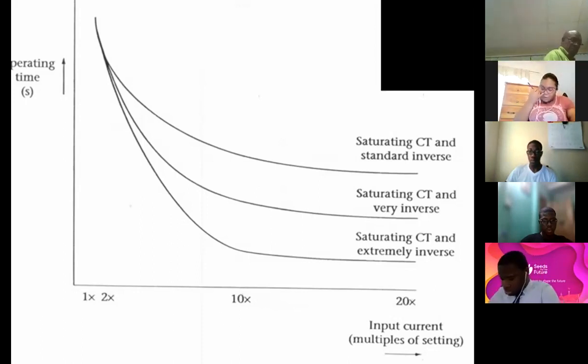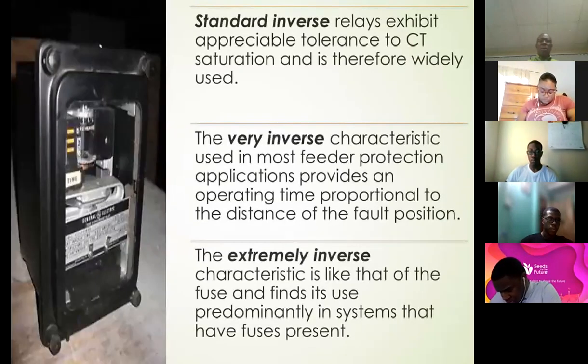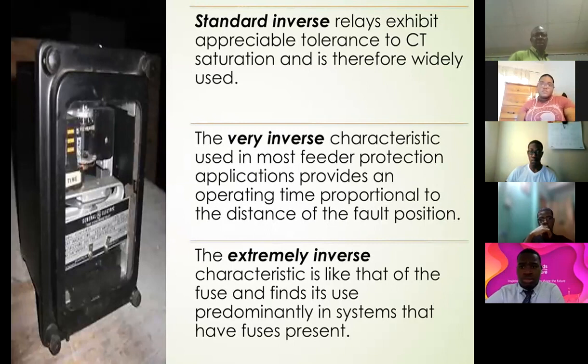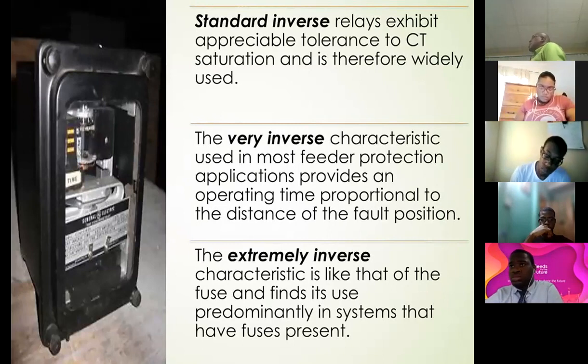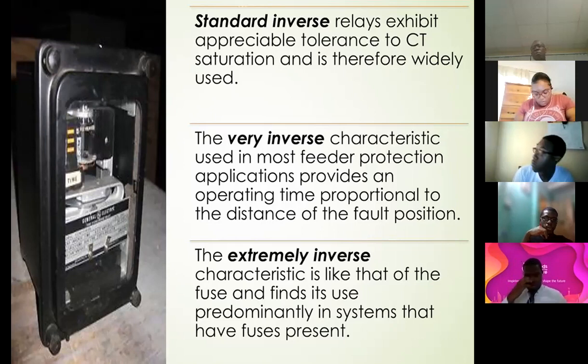So for your standard inverse, it is going to show what we refer to as appreciable tolerance to CT saturation. So where you're running the risk of having your CTs saturated, the standard inverse relay will treat with it.